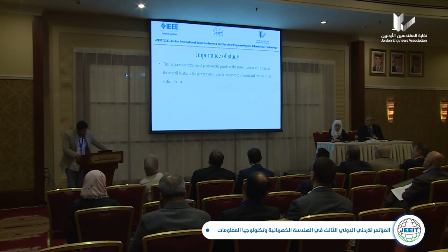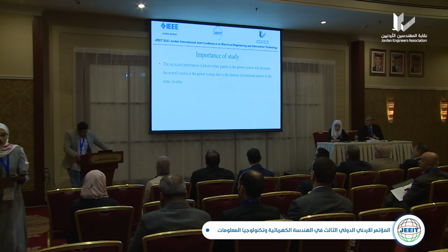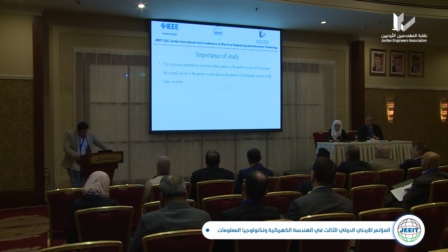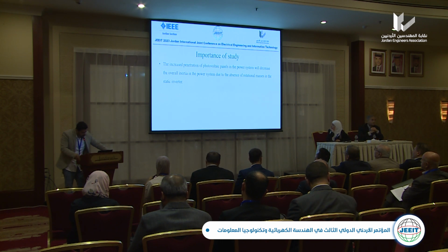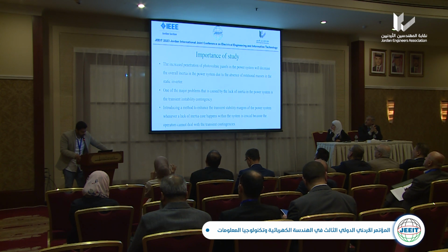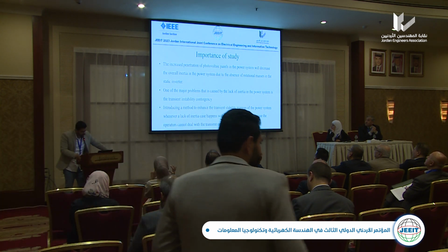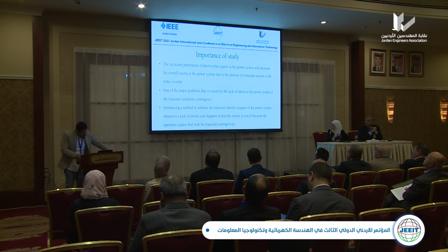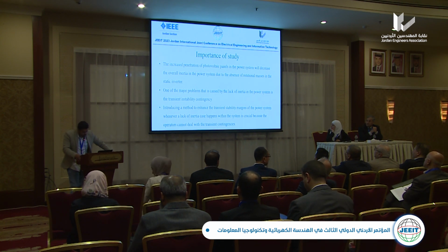What is the importance of the study? We all know that the increased penetration of photovoltaic panels in the power system will decrease the overall inertia in the power system due to the absence of rotational masses in the static inverter. One of the major problems caused by the lack of inertia in the power system is the transient stability contingency. Introducing a method to enhance the transient stability margins for the power system whenever a lack of inertia case happens within the system is crucial, because the operators cannot deal with transient contingencies, as they are in the millisecond range.